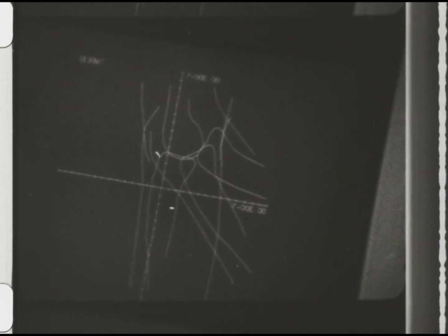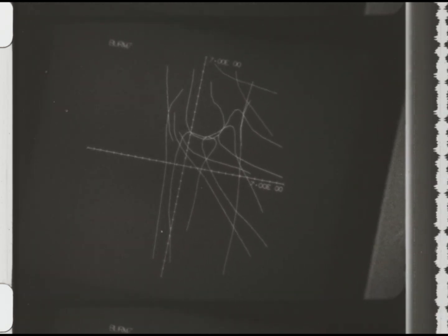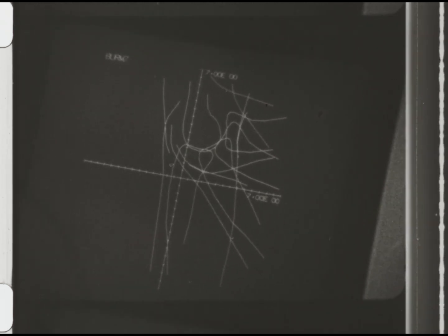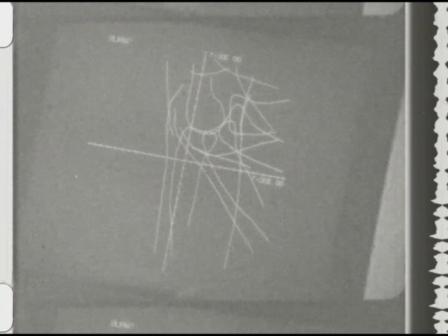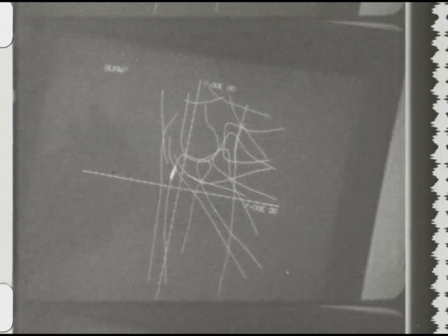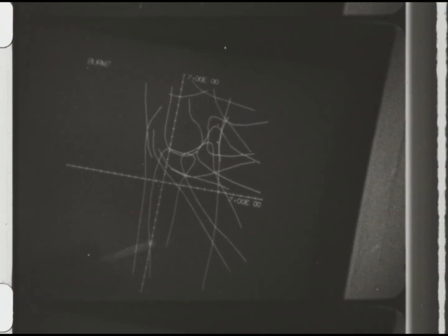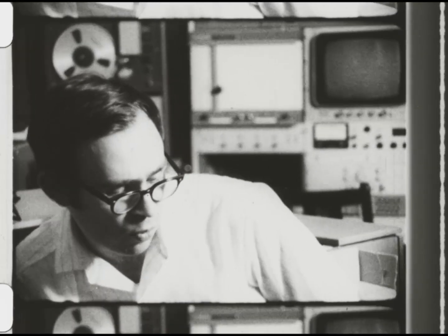Well, why don't we put up the transmission angle? Another piece of useful information in designing a mechanism is how good are its force transmission properties. We can put a scale of the transmission angle for this particular linkage up on the screen, and it will tick mark a number which is an indicator as to how good a mechanism this would be.